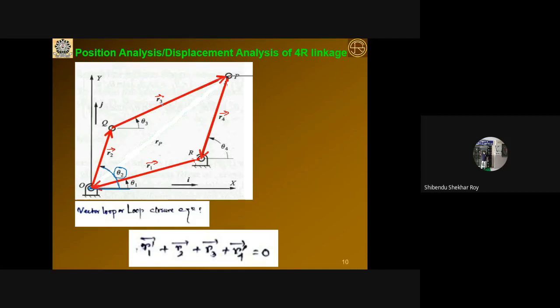Now, for the R3 vector, tail end is this one. At the tail end, you draw a line which is parallel to the reference x-axis. So these are parallel lines I have drawn. Now that means this direction is the same as the positive x direction, a localized frame attached basically. Now this will be parallel to the y direction. At the tail end you have to measure with respect to the positive x direction, and that means this will be theta 3. So got my point?